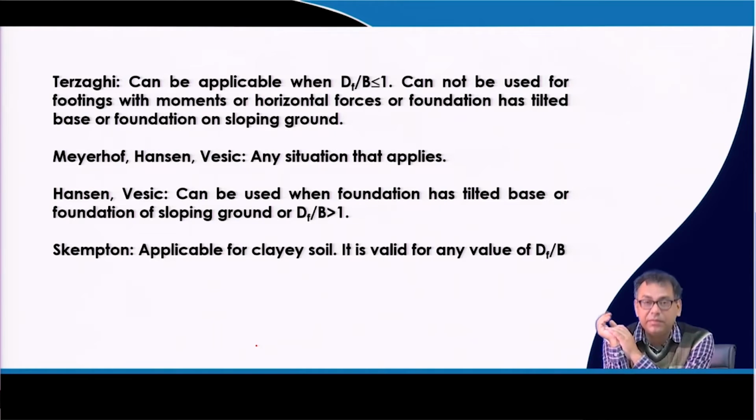And if your foundation base is within the width, you can go for the Terzaghi for simple conditions, but if there is a different loading condition or moment or other conditions, you cannot use the Terzaghi. So, depending upon your requirement, you have to select which one you will use, and as I mentioned, Meyerhof, Hansen, Vesic, all these equations can be applicable.